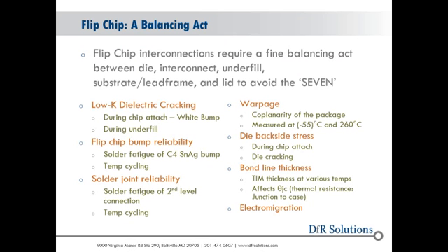I'm also worried about solder joint reliability. So the flip chip interconnection can actually influence the reliability of the second level interconnect. We don't want to transfer the weak spot necessarily from flip chip bump to solder joint, especially if that transition makes second level solder joint reliability much worse. We have concerns about warpage.